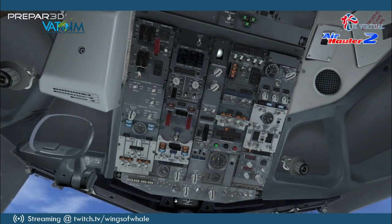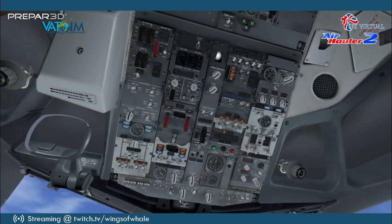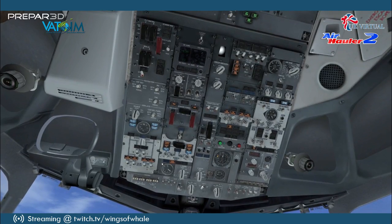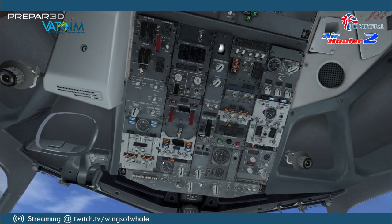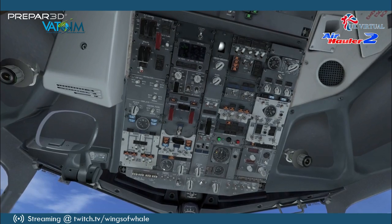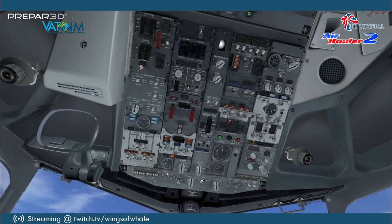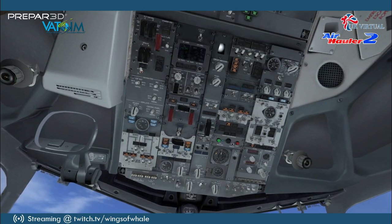So I click it to on, and then I click it to start, and you can hear the click of the APU. And if you watch this gauge, the APU gauge, you'll see it'll rise all the way to the end, and then it'll drop back to about 4. So there we go. It's started up now, and this takes about 30 seconds or so to start the APU.